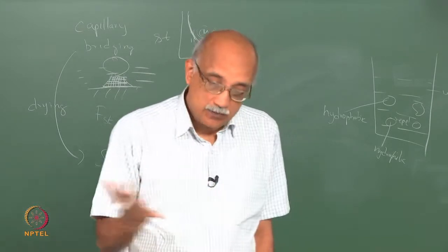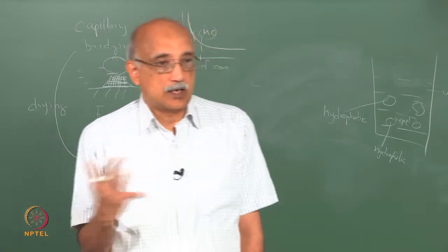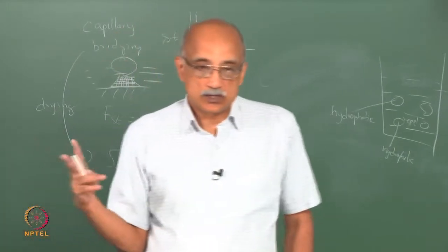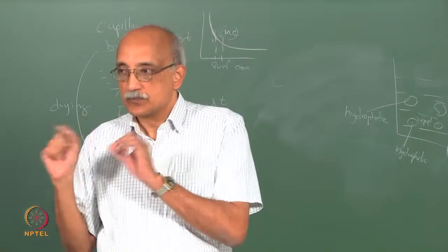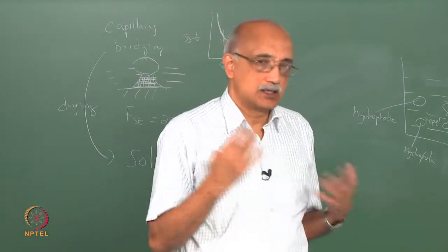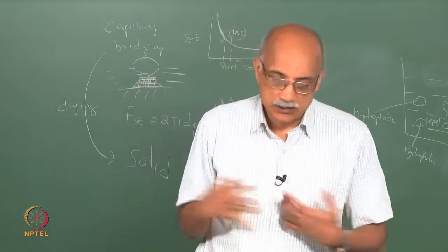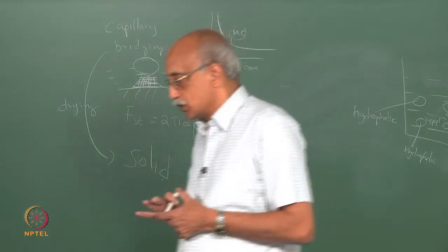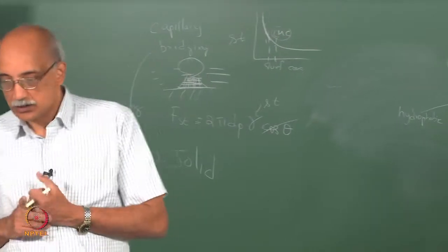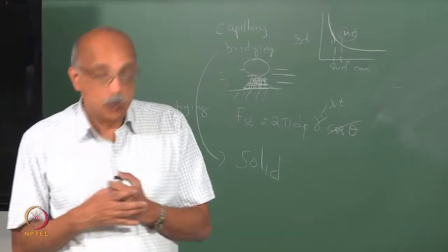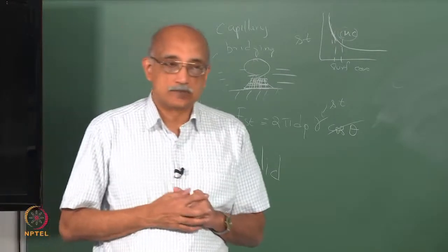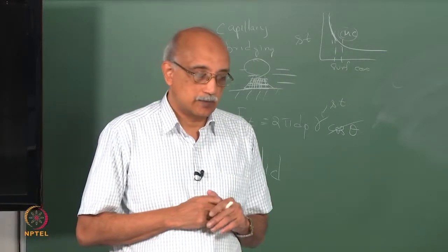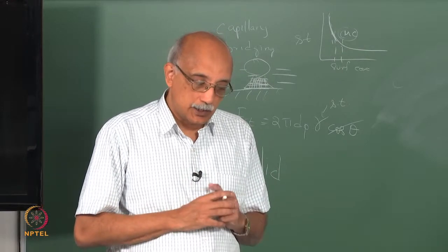And again, in the extreme case, if you have particles that have highly cohesive tendencies, you can start to see solid masses moving through rather than individual particles, and as you can imagine, that can be very difficult for process equipment to handle. So, cohesion certainly has different implications, I would say more far-ranging implications for mechanical operations compared to adhesion. So, it is important to understand cohesion in some detail.